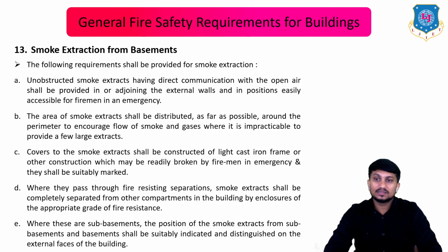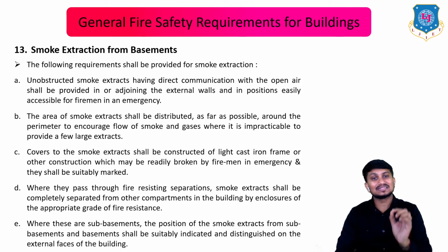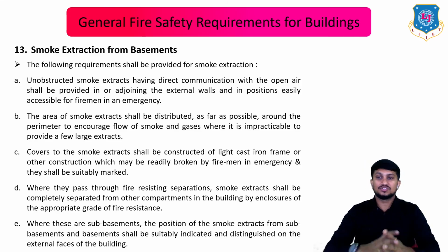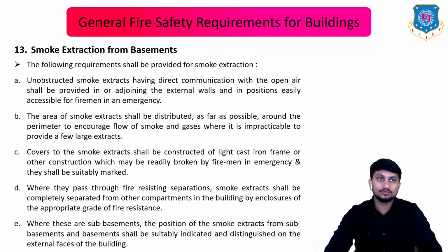Okay. Then third, covers to the smoke extracts shall be constructed of light cast iron frame or other construction which may be readily broken by firemen in emergency and they shall be suitably marked. Okay. So in this way, the firemen can easily get into the basement and do the rescue operations.